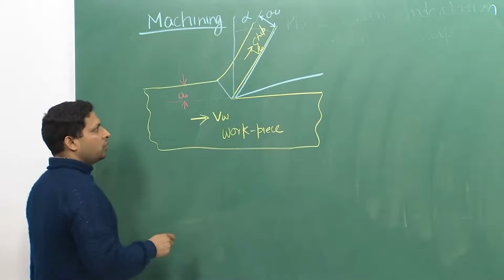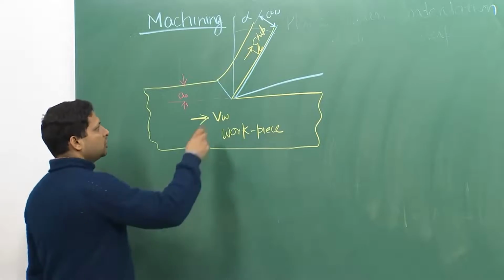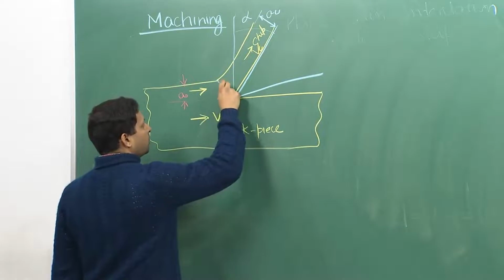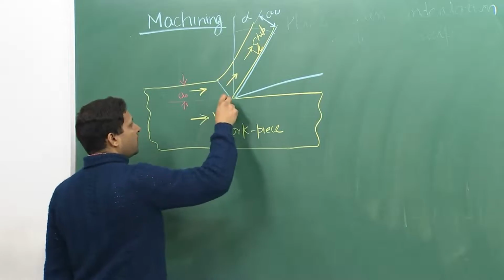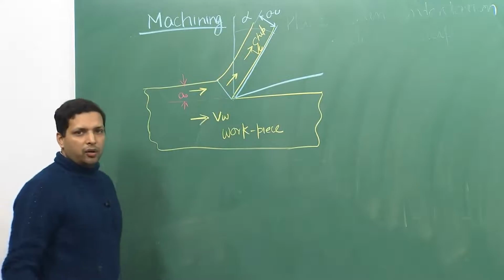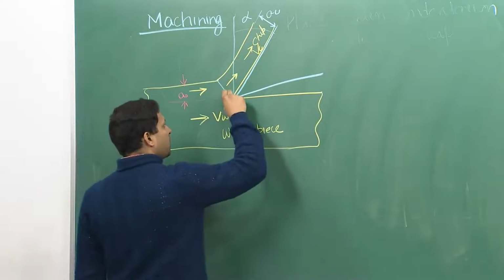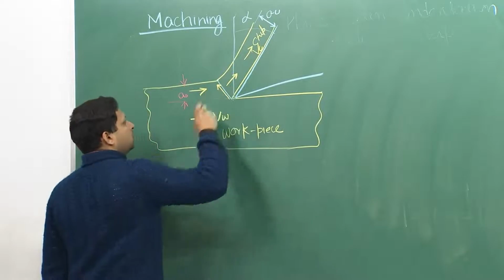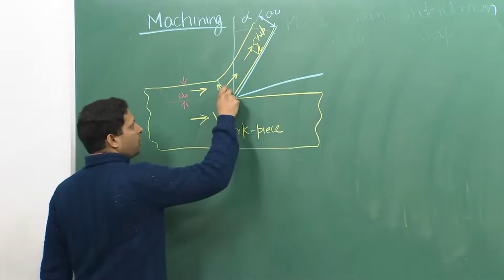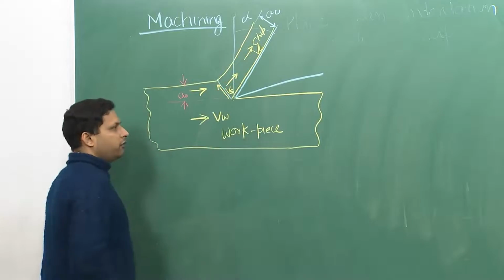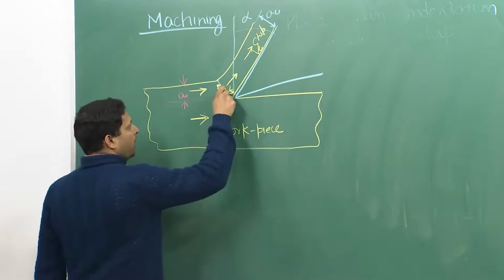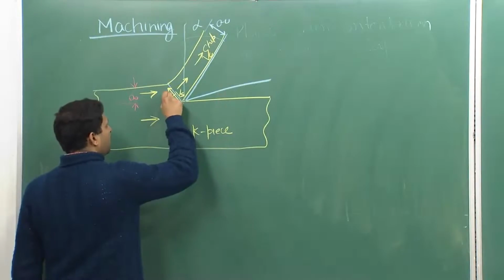Second is to denote the moving parts. So, here are the moving parts. This is moving here, and when it crosses this line, it starts to move here. So, there must be a discontinuity here, which is your shear, where the internal shearing is taking place. So, let us call it Vs, that is the shearing velocity, and there will be an implicit angle over here.